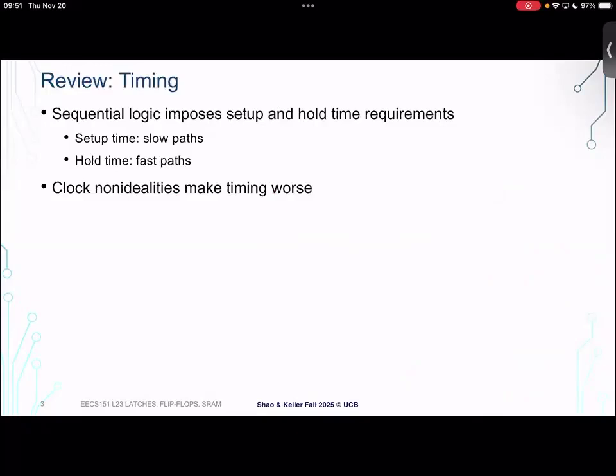Okay, so this wraps up our discussion about timing analysis, which we went through on Tuesday. We talked about how sequential logic imposes these two key requirements for setup and hold time. Setup time is violated when paths are too slow. There are lots of ways to fix it, but in a pinch, you can always just reduce the frequency. So setup time is pretty much never going to kill your chip outright.